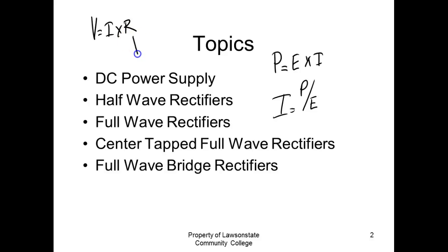So every wire has a resistance. Every wire has a resistance. And think about the wires running from the Tennessee River down to Bessemer, Alabama. If you had 1 ohm of resistance in your starter leads, the wire would drop more voltage, and no matter how good your battery was, that's one of the first things you check if your car don't crank.